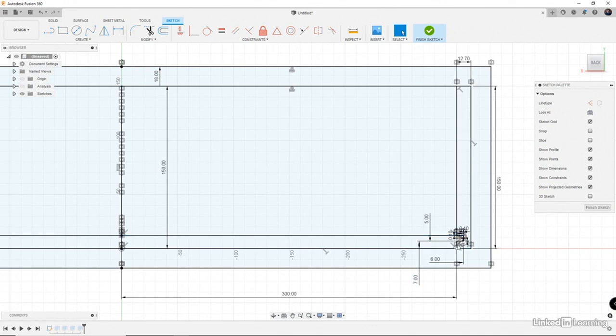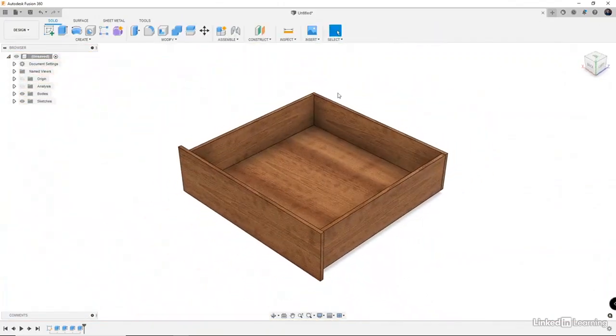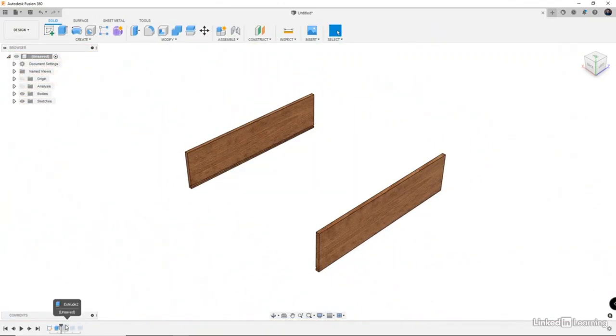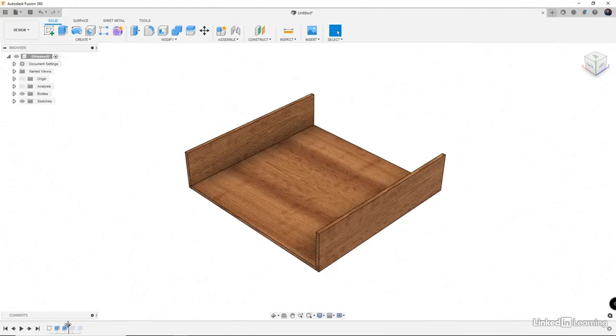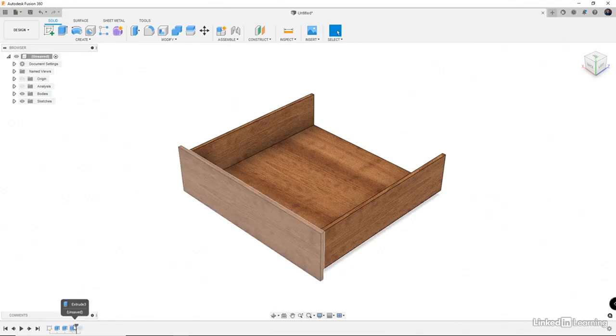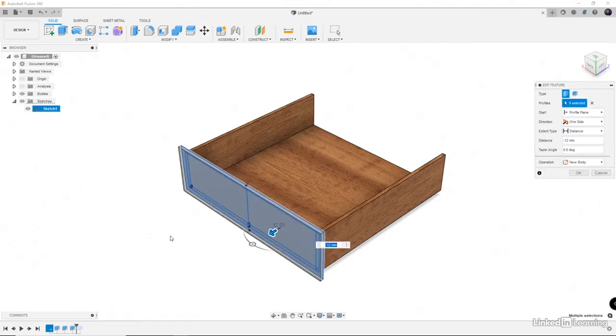And then once you have this built into geometry, you can mirror it to the other side. And then once that's done, my basic approach, let's go back in the timeline. I'll just kind of go backwards. I basically, very simple, extruded either side. I then extruded the bottom, and then I went ahead and extruded the face. Now the sketch is over here, so that's all super simple. The only thing that I selected is, when you do this, because the faces are touching, the operation, you can say join, cut, intersect, or new body. I did new body for everything.